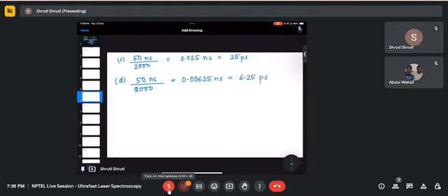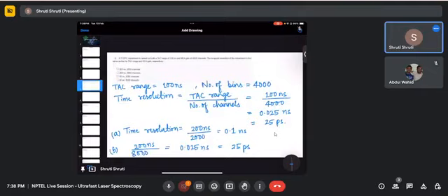There are multiple experiments going on in TCSPC, as you know. Suppose one photon came at 3 nanoseconds; again, if a photon comes at the same time, 3 nanoseconds, then the capacitor should get charged equivalently to show the time as 3 nanoseconds. But it may not always be the case, because of the electronics involved, there will obviously be error in these things. So this constant fraction discriminator is an instrument to handle that part.